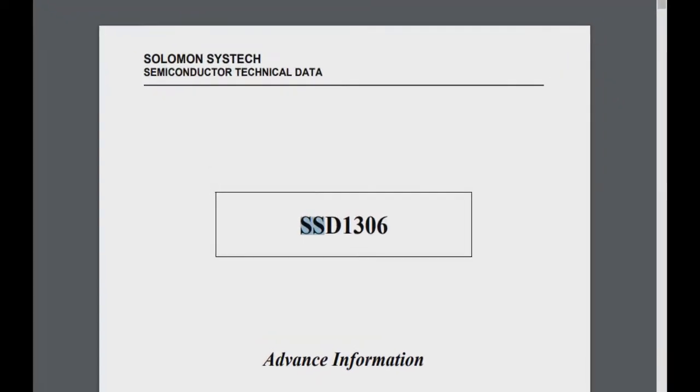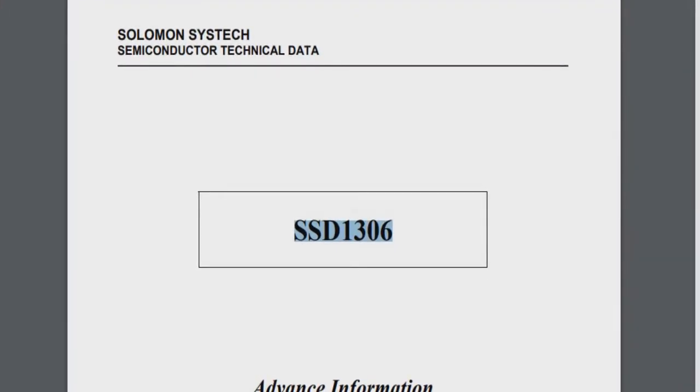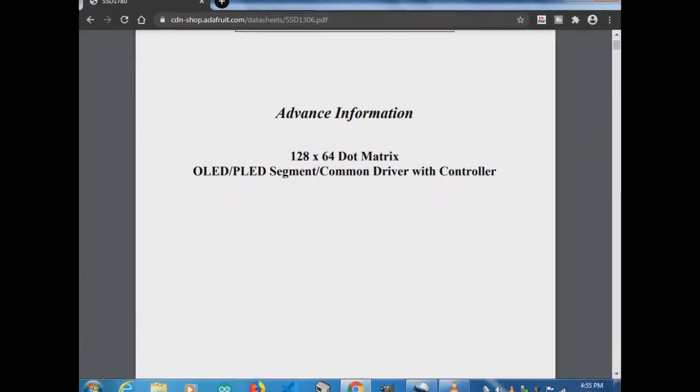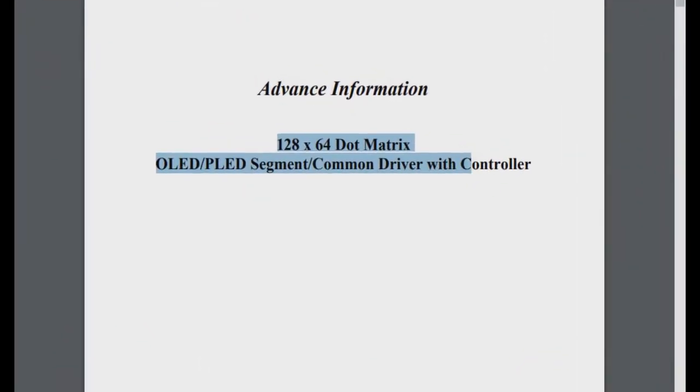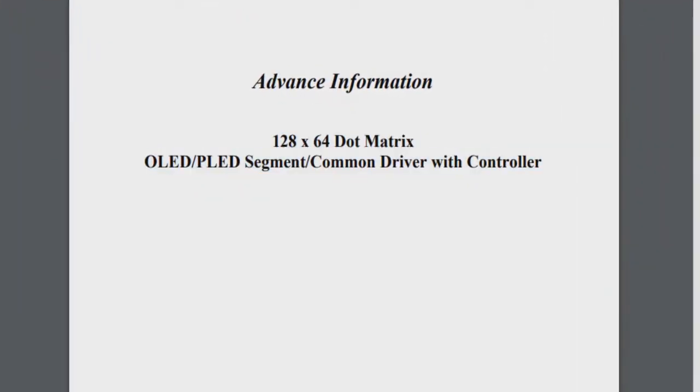Next, we can talk about the driver of the display. It is the SSD1306 monochrome display driver, which can control 8 segments which contain a total of 8192 pixels. This driver has about 1 kilobyte of RAM on it.